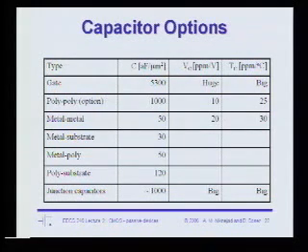Okay, metal capacitors, why do they have a voltage coefficient? I don't know, actually. It seems like if you build metal insulator metal, it should be pretty damn linear, right? Maybe this is a typo. Maybe you're using a weird insulator, and that would give you a problem. If you're using an insulator with a very high epsilon value, not native oxide, then there could be some nonlinear effects, right? You could have dipole moments that change direction as you change the field, and basically, if you're fighting, let's say, kT energy on those dipole moments, then the higher the field, the more capacitive energy, the more dipoles you're likely to align. So it would give you a voltage coefficient. But otherwise, I don't know why it would be there.